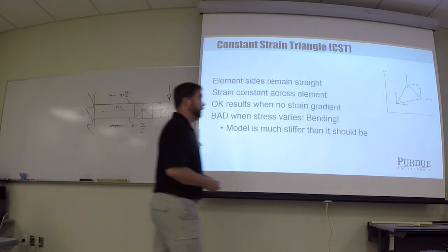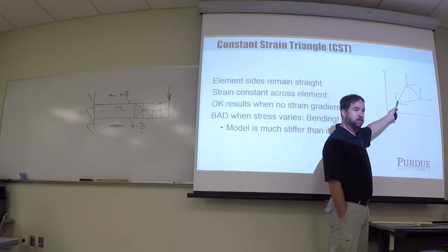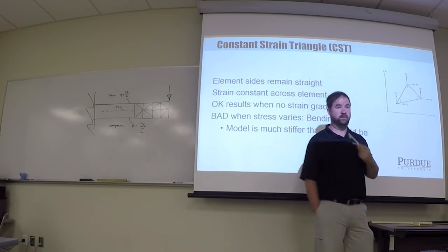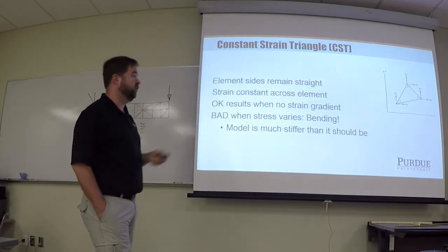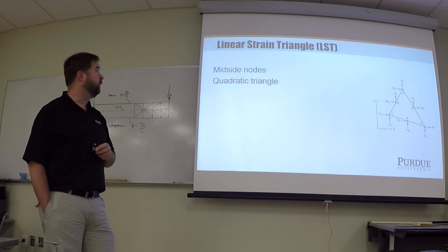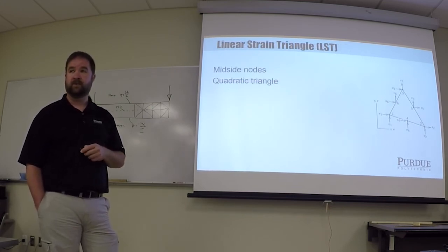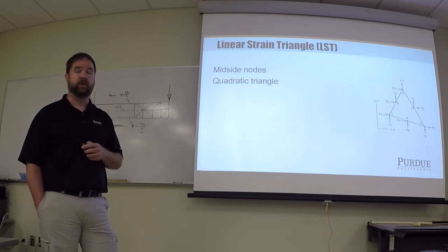Notice that this picture here would be just the plate. So it doesn't have the additional, so it just has the 2 degrees of freedom for the linear translations. Okay, if that's a shell, then it has 6 at each node. 6 times 3 is 18. If I use LST, how many degrees of freedom do I have? 36. 6 nodes times 6 degrees of freedom is 36 degrees of freedom on each element.